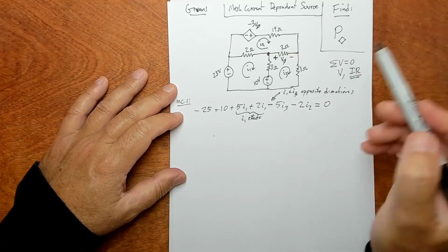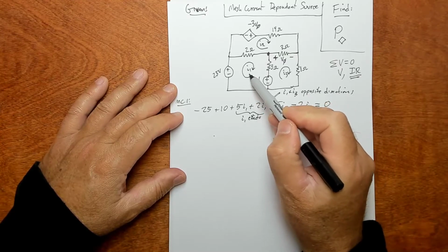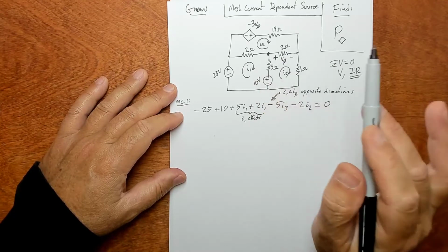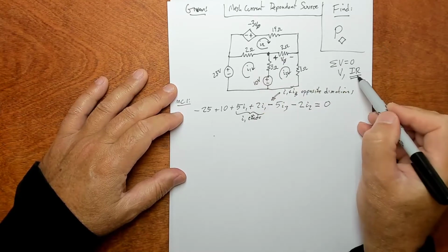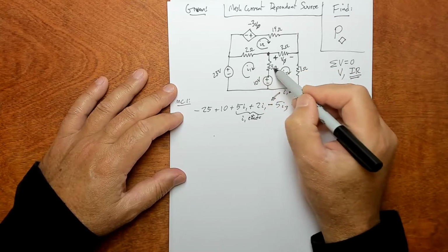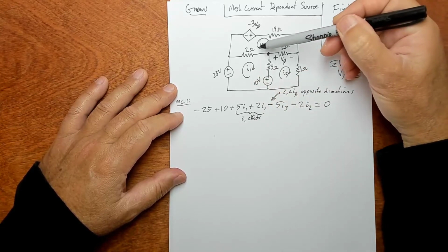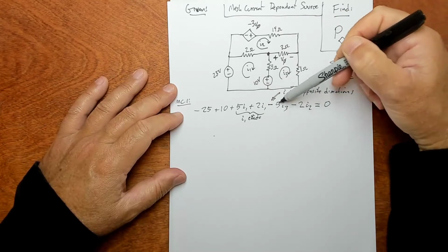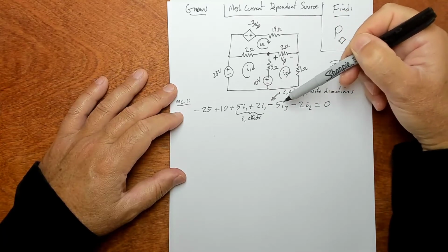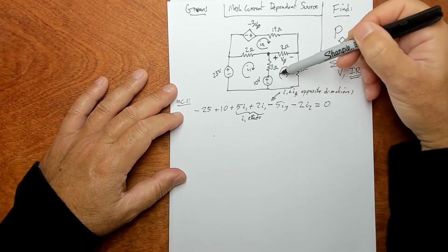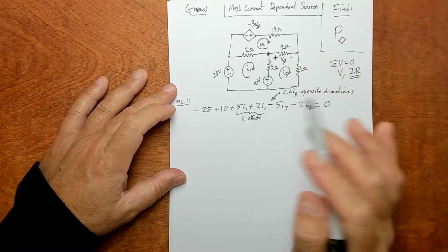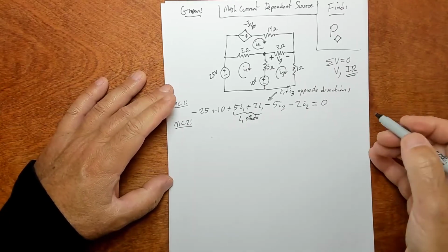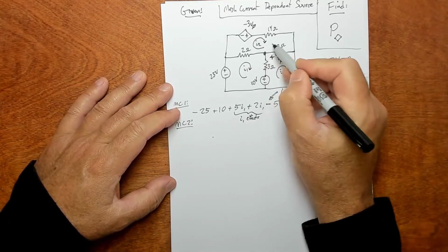Okay, so just real quick, we went around here, we did the V's and the IRs. Then just for the resistors, we do the IR superposition terms. Okay, so we did 2I2 and 5I3 superposition terms. And they happen to be negative terms because the currents disagree. All right, that's it. That's mesh current method. And then you do that again. So you go around loop 2, okay?